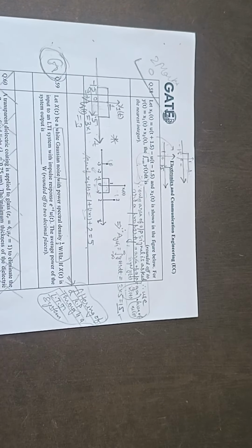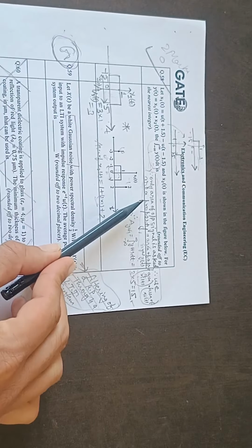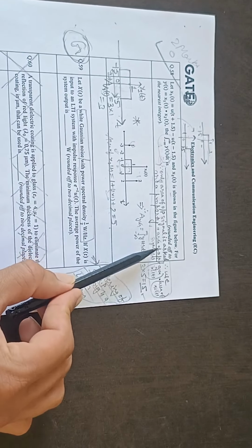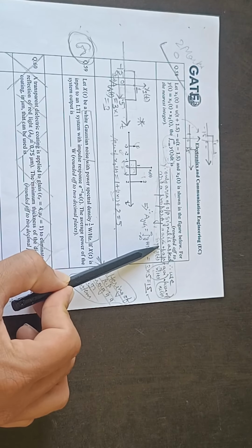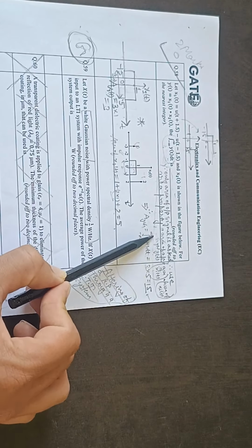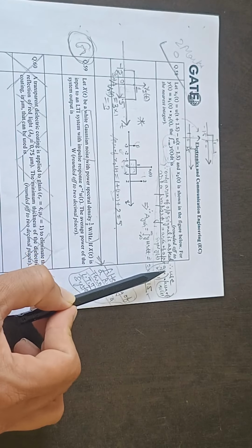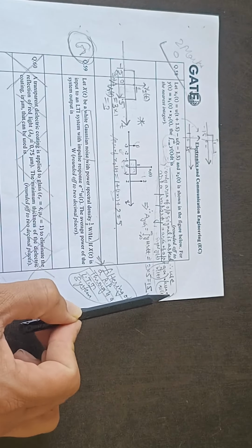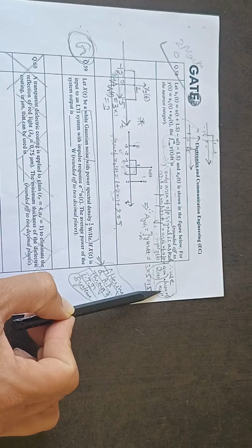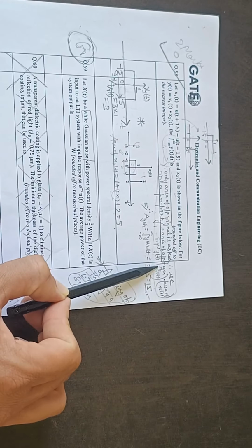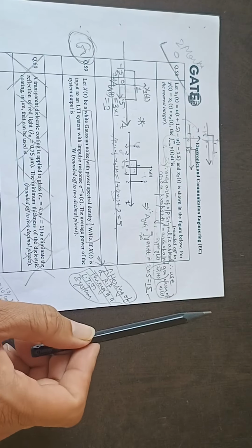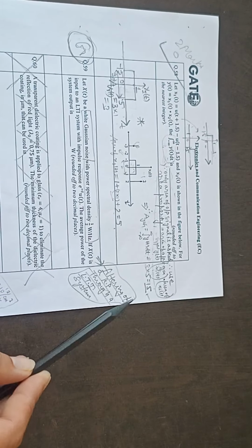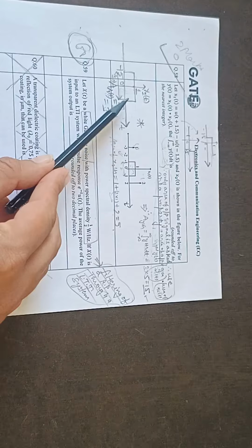So here we will use the area property of continuous time convolution: since only the area of the output signal is asked, the area of output signal y(t) is nothing but the area of x1(t) times the area of x2(t). So if you take the product of both areas of the input signals, we get the output area. So the area of y(t) is the product of these two areas.